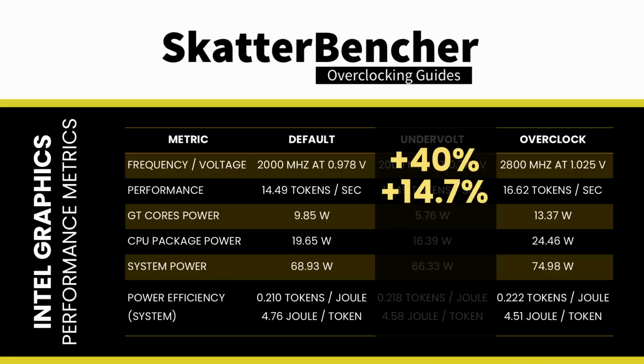While it doesn't sound that amazing, bear in mind that the operating voltage only increased by 4.8% from 0.978 volts to 1.025 volts. The system power consumption increased to 74.98 watts, an increase of 8.8%. That translates into 0.222 tokens per joule or 4.51 joule per token, an efficiency improvement over default by 5.45%.